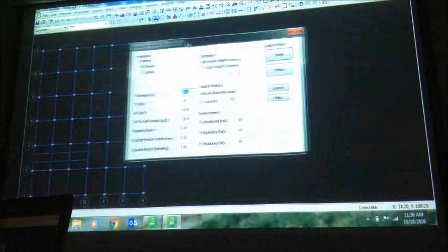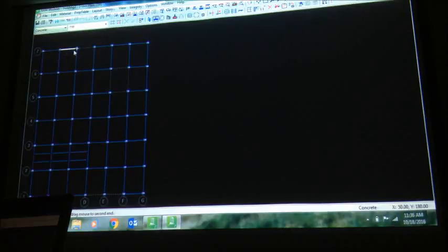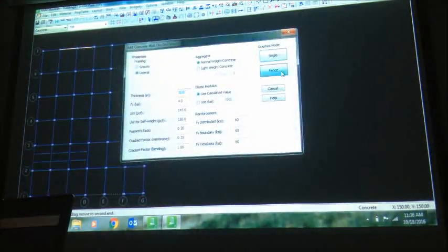So let's place walls, add on grid. It will come up with a 10-inch thick wall, which is fine; whatever thickness you want is fine. The only thing is, shear walls are usually the lateral resisting system, those are for earthquake. So I will click on lateral. You can use single, or you can do a fence.